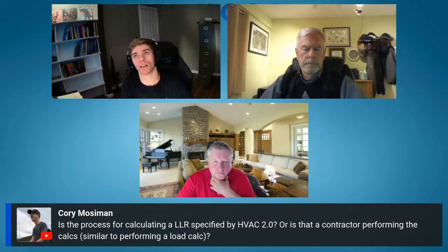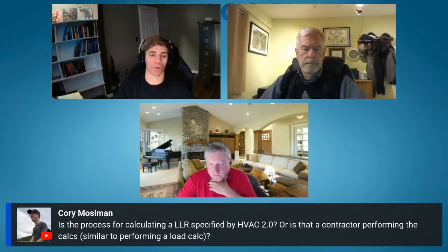You can think of it really, and if you want to use it starting out, the reason we come to the likely load range is a lot of us have done enough comfort consults where we've done blower door testing. We have looked at run times, and we've watched houses function to where we got to the point where, okay, a particular type of house of a certain size, we know it's going to fall within this range of sizing because, if it's bad, it's going to be on this end, or if it's good, it's going to be on this end. And then we go test just to verify, essentially.